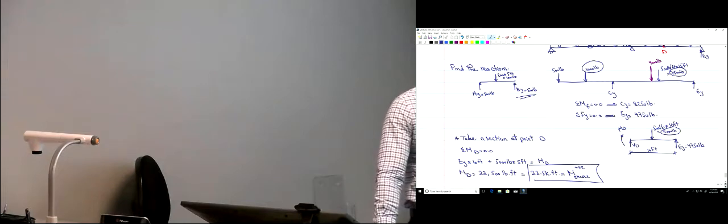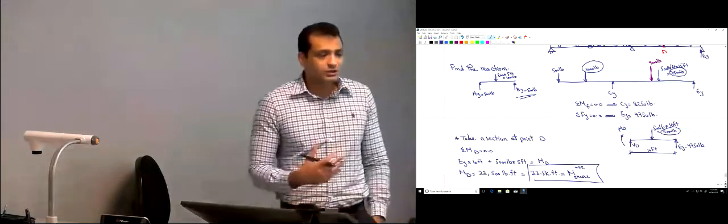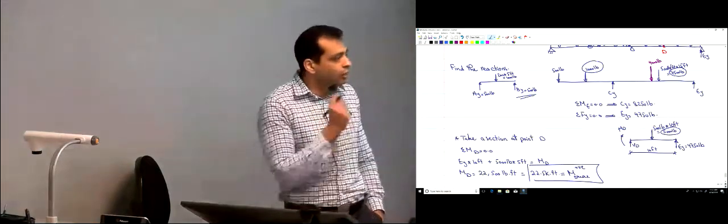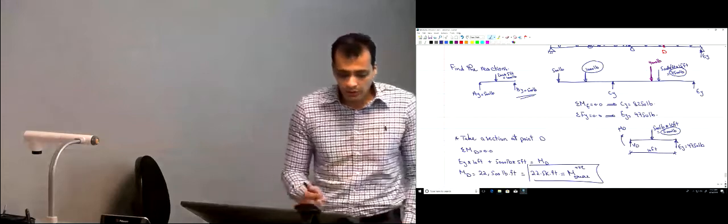You see how powerful those influence lines are. This is why we learned this topic about the influence line. The objective of using the influence line is to know where to put your load to maximize any function, whether it's the moment at a point, a shear at a point, or a certain reaction. You can only answer this question, where to put the load to maximize a function, through the influence line. Nothing else can answer this type of question. Any question?